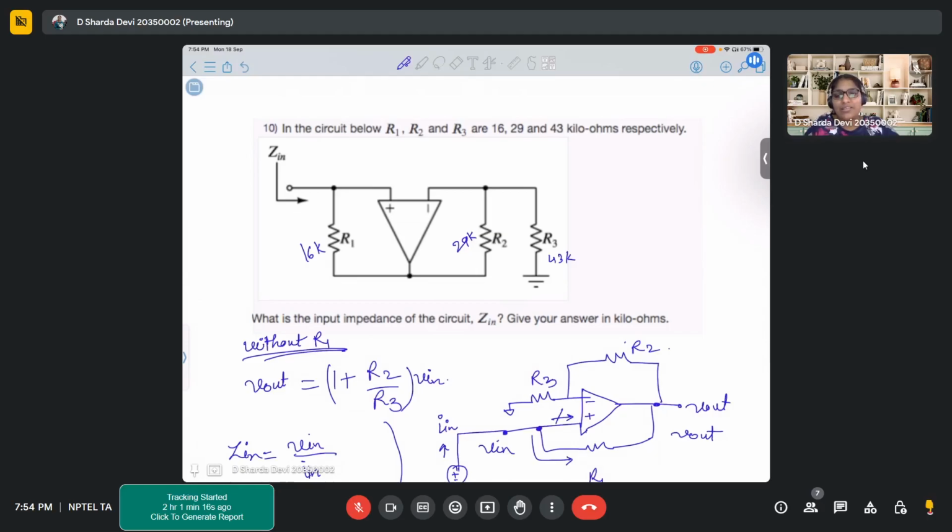So generally when we say, okay, what will be the gain formula? What is the gain formula? We generally say GM into Z out. But if it is a CS amplifier, it should actually be minus GM into Z out. That minus is very important for a CS amplifier.